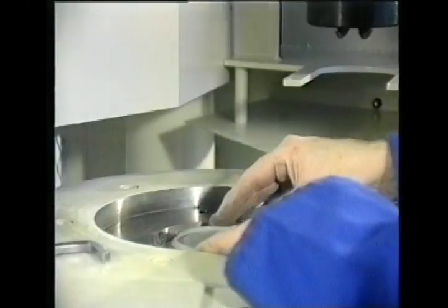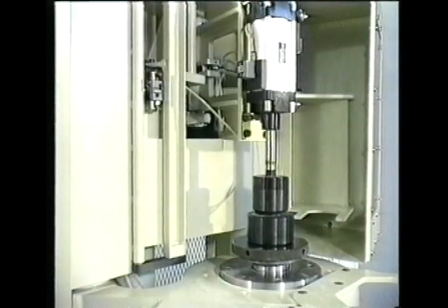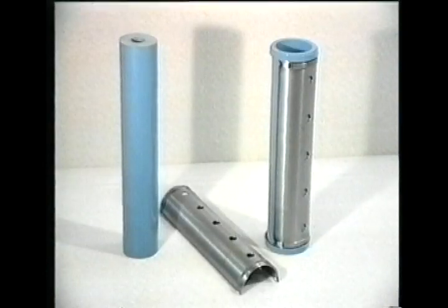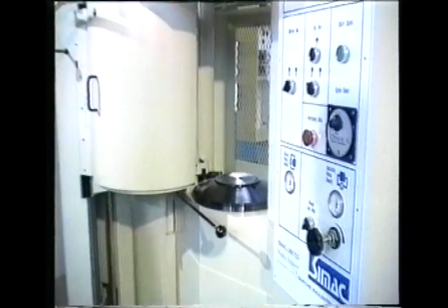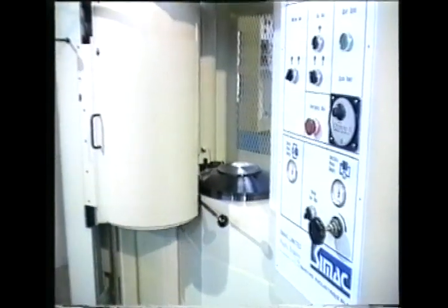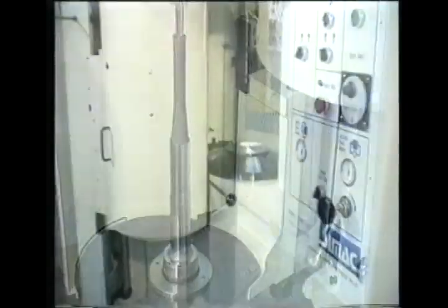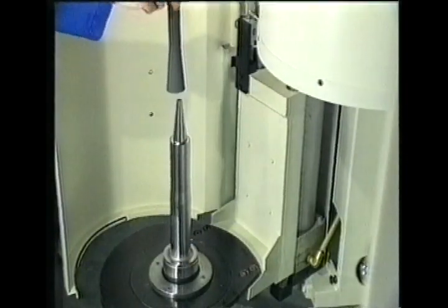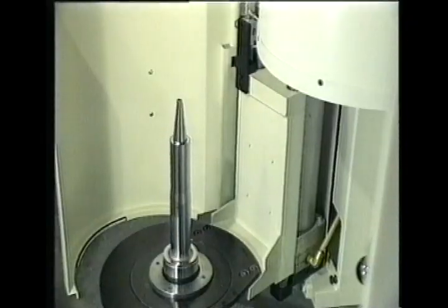Fixed molds are filled and sealed within the press, and the pressure is applied behind a membrane integral with the mold. The bottom closure lowers to remove the part after pressing. Because the fluid never touches the mold, this is called the dry bag process.